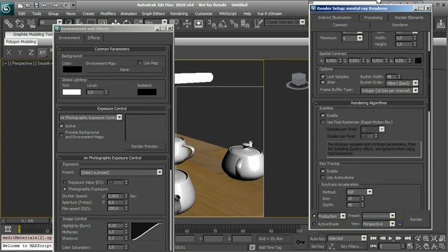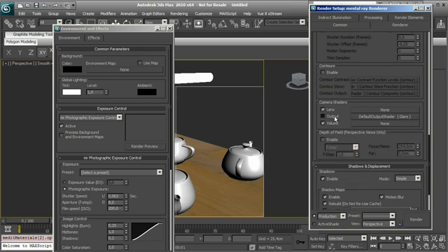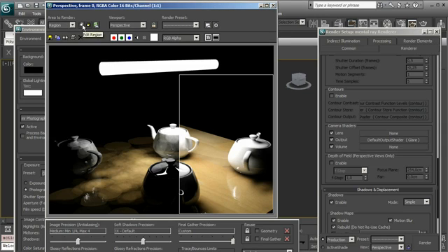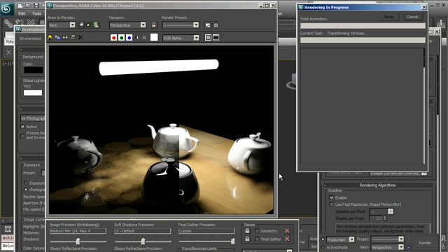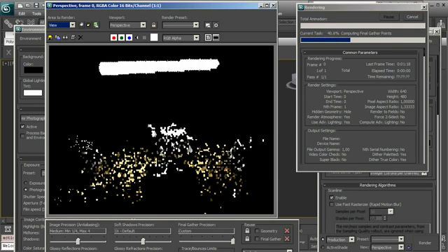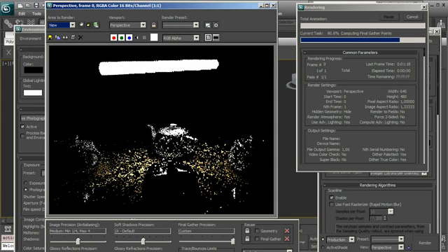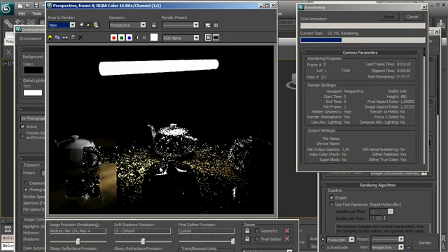So let's go back and let's use 150 just to make some tests, and we can go inside the renderer and we can set on the output glare, and let's see how it works. Let's change to view and let's make a test. Obviously the quality for the final gather will be really low, but actually I'm just interested to see the glare effects, to have some kind of glow and a halo over the tubular neon.